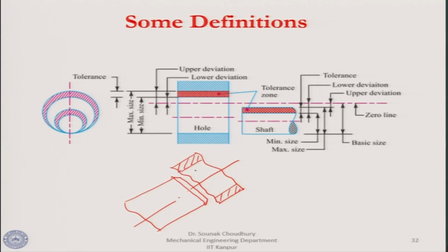In that case, the internal diameter of the hole should not be more than the outer diameter of the shaft. That is one thing. Now, how much more? That means the shaft diameter should be a little more than the internal diameter of the hole, so that it can sit very tightly. That is the concept of this. A tolerance has to be given accordingly.